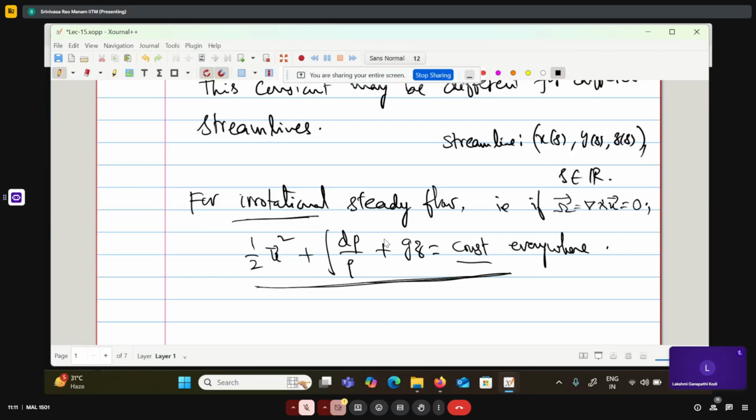That is a constant in the entire fluid. It is true, so it can be a compressible fluid also. For compressible irrotational motion also, the Bernoulli equation is true, where irrotational means you have u equal to grad phi, a scalar function called the velocity potential. Now what we consider is we don't remove del cross u equal to 0, but we remove the dou u by dou t term.